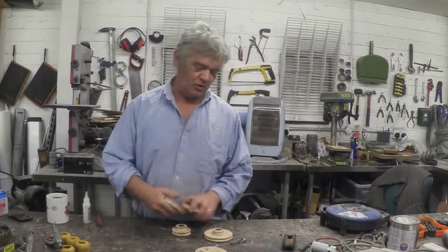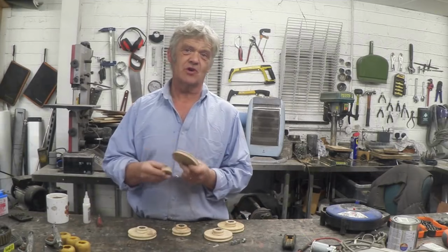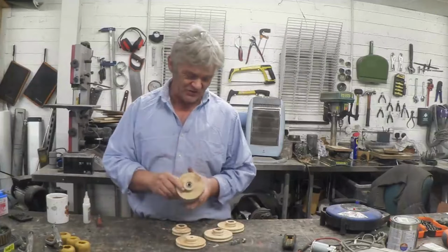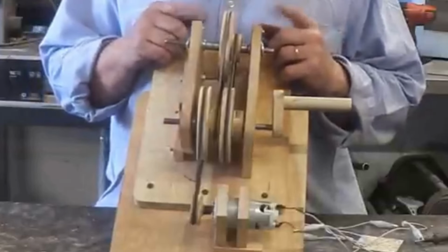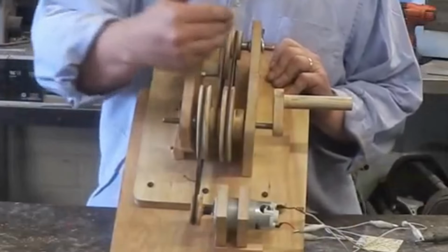in. This bunch of pulleys, now they're really easy to make. They're just a couple of discs of wood, got a groove cut in them, glue one on the other, drill a hole and stick some bearings in, you'll get some pulleys. And there we go with our pulley arrangement, big, little, big, little, big, little. I've just put it in a cradle and I've got a couple of bolts on here. I tighten those bolts and it tensions the belt.